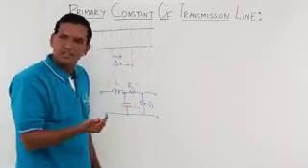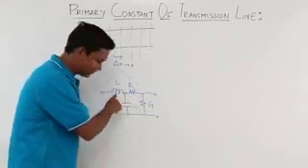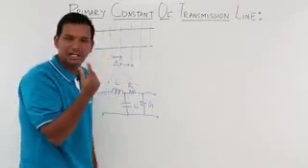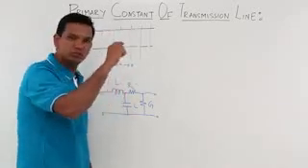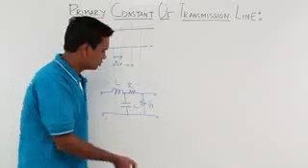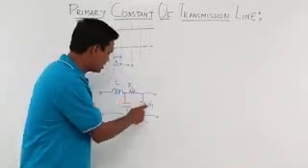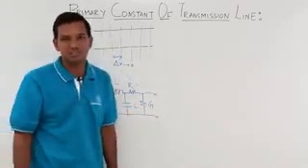At high frequency, it will have inductance, which we have denoted by L. Between the two wires, it acts as a two parallel plate capacitor, so we will have capacitance. Between the wires at high frequency, there may be chances of charge leakages, so that constitutes the conductance, right? So this is L, R, G and C. These are actually called the primary constants of the transmission line.